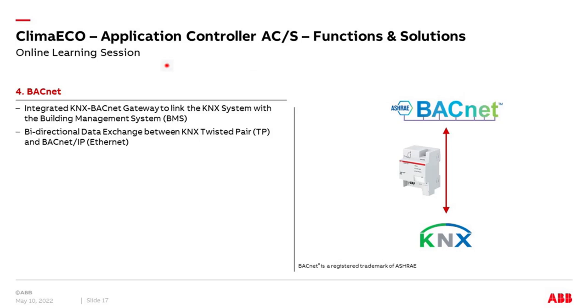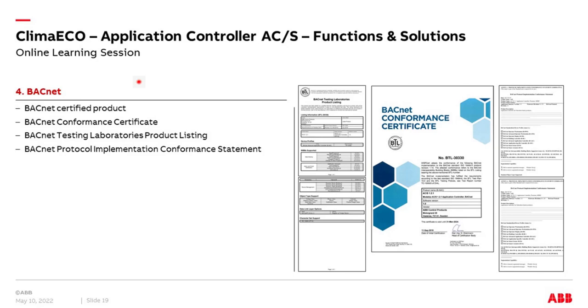Yeah, and the BACnet gateway. We have an integrated BACnet IP to KNX gateway with bidirectional communication. So I can send from KNX to BACnet and BACnet can write into KNX devices. So it's a full KNX BACnet gateway. Yeah, and as it is also a BACnet device, it has also a certification behind. So it's a BACnet certified device. There are some documents you can find on our homepage, just for your information. Not only a KNX approved, but also a BACnet approved component.